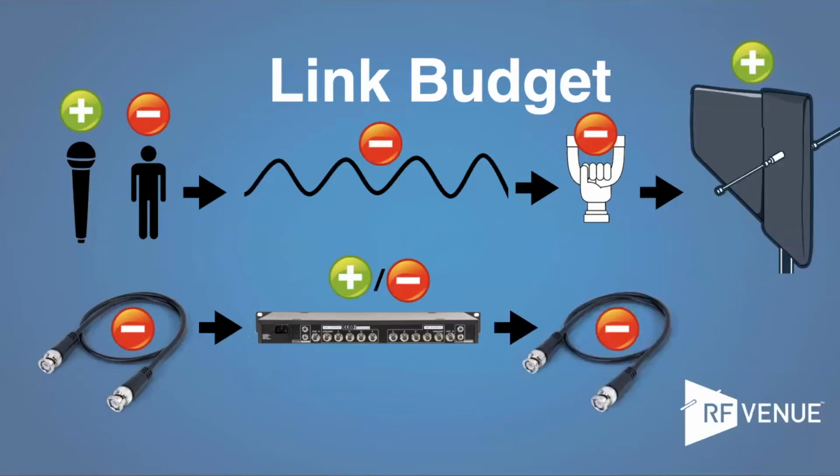And now, of course, we're going to need another, usually short, cable that's going to go out. So we've got another loss. If this is a foot or two, this isn't very much loss. A fraction of a dB for the cable itself, a little bit for the BNC connectors. We can get down into the weeds and figure out all the tiny little bits later, but just get a general feeling for what's going on. There's not much loss here, but count a dB or so.